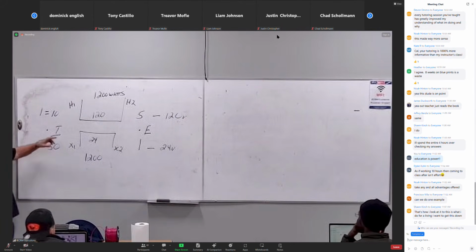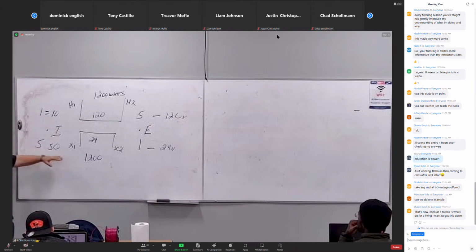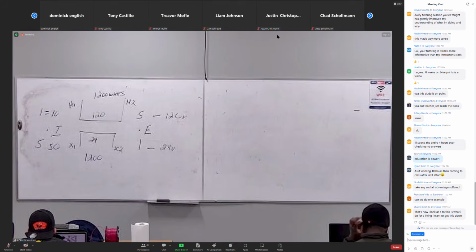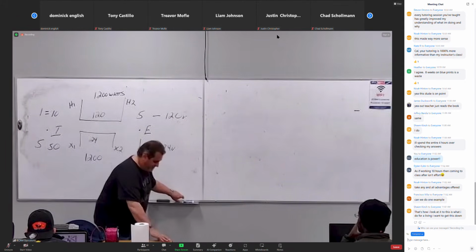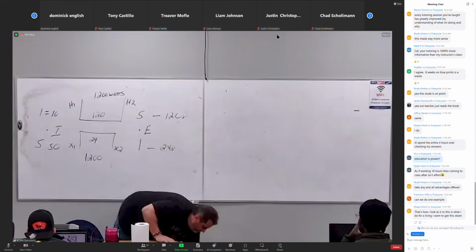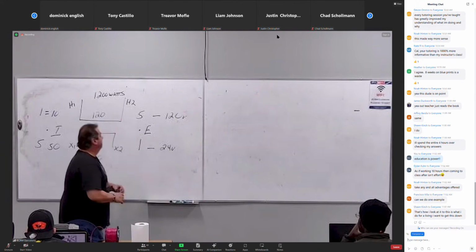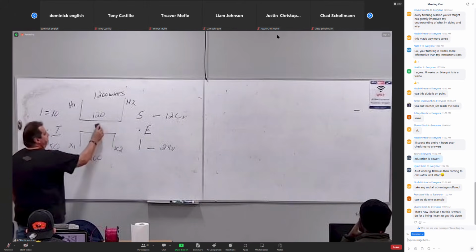We shipped it clear across the office building at 120 volts because it only drew 10 amps. I was able to push number 12. Once we got to the load, we had to push number 8 because it was 50 amps. That's the beauty of being able to transform power and voltage. Think of it on a larger scale though. So, ratios don't change.